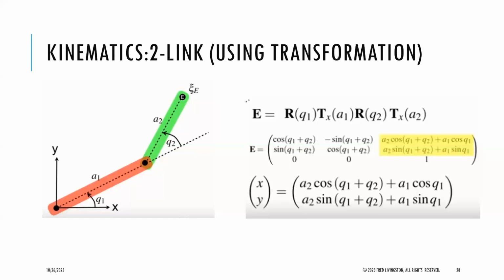We know the rotation matrix, we know the translation matrix, and we just do the thing. I could do any kind of configuration I want. I could have the robot coming out of the page, whatever, and I just do a transformation through each one of those and compute that. That's going to give me a 4x4 matrix, which gives me the forward kinematics of the system.